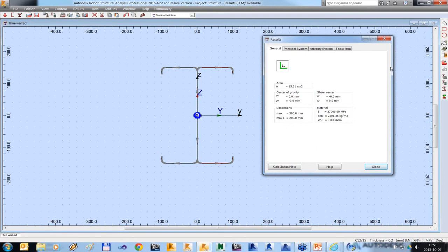First, which code verification formula is going to be used, which verification path is taken, and then, based on the slenderness of walls calculated according to the parameters you entered, which class the section is going to be assigned to. That's for the general rules, but all the properties are used as calculated for the exact shape you entered.